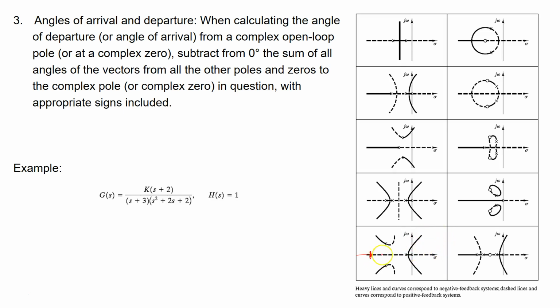But exactly opposite of that now, if the feedback is positive, how many total zeros and poles are to the right hand side of this test point? 2, since that's an even number, so that point belongs to what? Root locus of the positive feedback. And so the rest of it too.